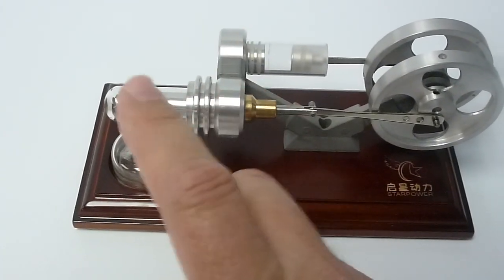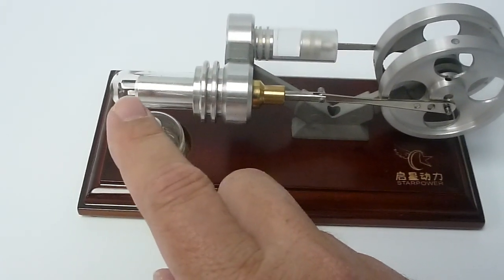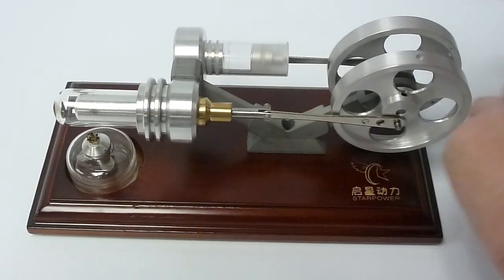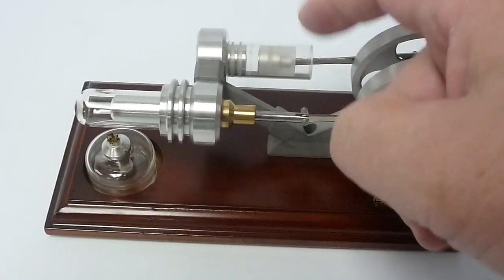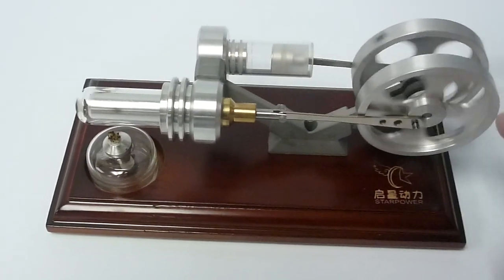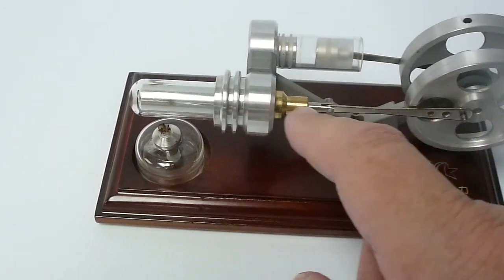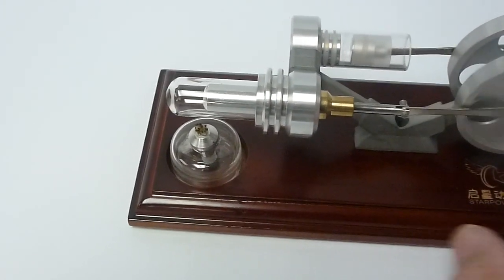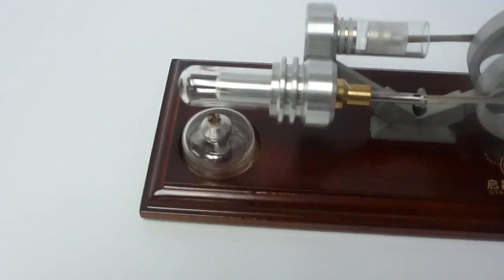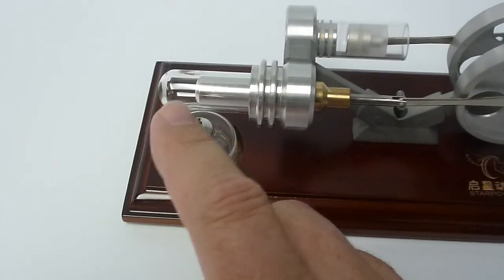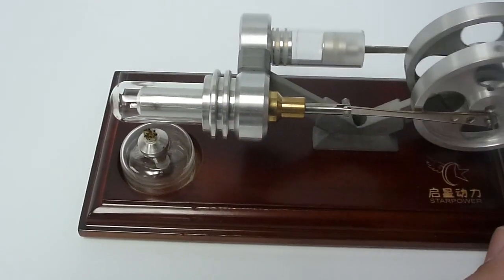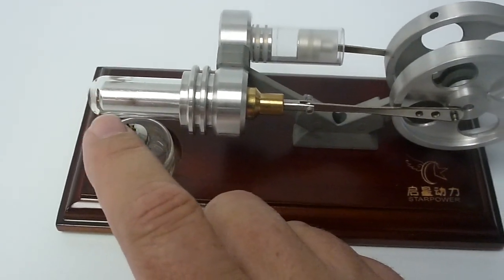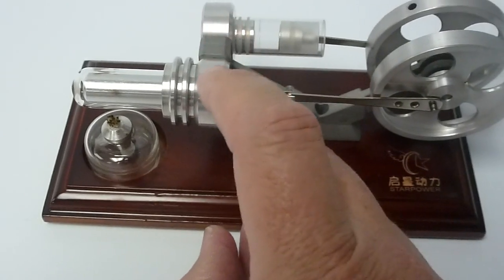So the gas that's in here heats up in this hot chamber, and this piston right here is the one that's actually pushing on the flywheel and giving it all the power. We call it the power piston. The flywheel is then telling this little connecting rod here to move this thing called the displacer back and forth in the hot chamber. So right here you've got all the air on the hot side of the chamber, and when the flywheel moves over to here, the displacer has pretty much pushed all that air back into the cold side.